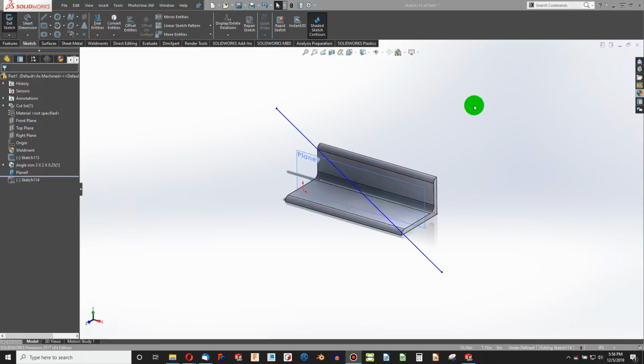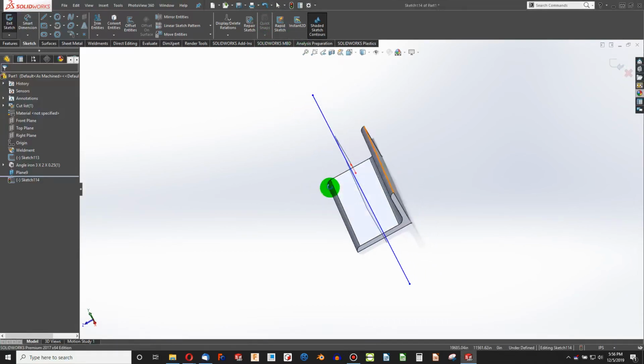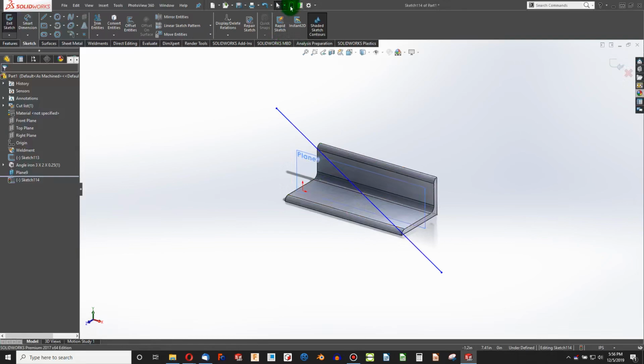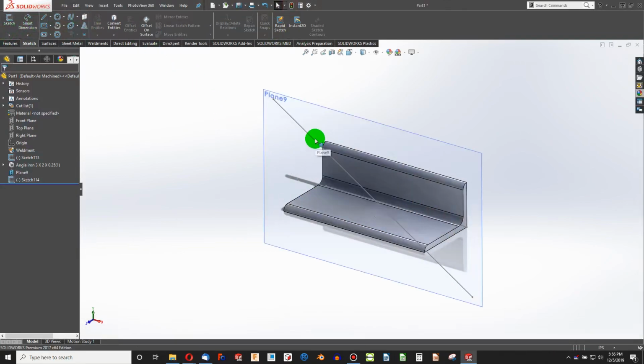So let's talk about different strategies of using angle iron and being able to intersect that with pipes. Here I've made an offset plane that intersects with my angle iron, and if I just do that weldment feature, it goes right through like you've seen before. So let's try a few different ways of getting it to cope.